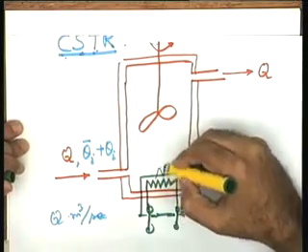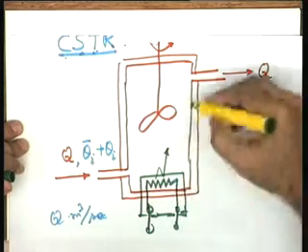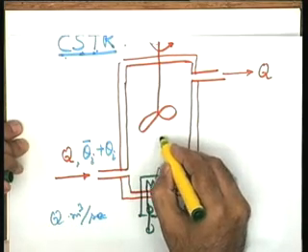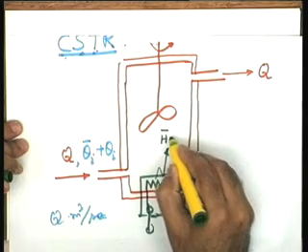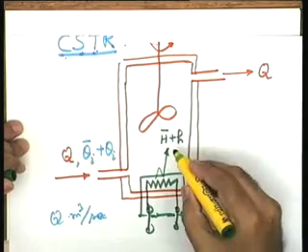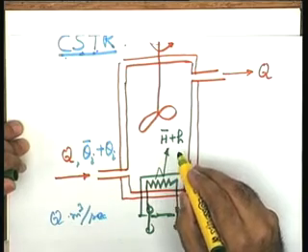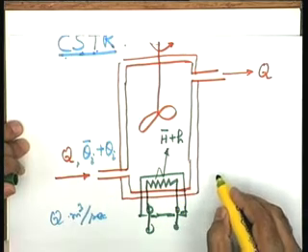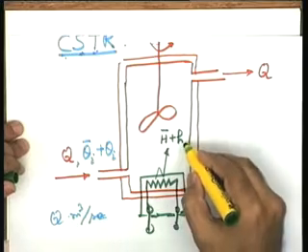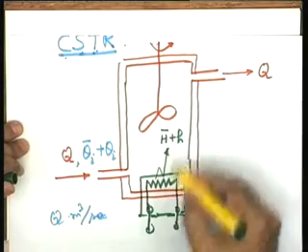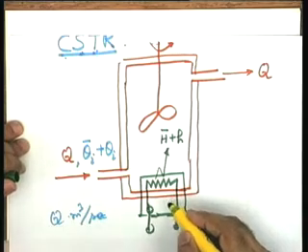So, naturally this you will say is the heat given to the liquid, and again as per the terminology used earlier, I will be using H bar plus H. You have to very carefully note this point. H bar is the steady state heat flow rate, the units of heat flow being joules per second, and H is the perturbation in the heat flow rate, which in this case may be a controlled perturbation.